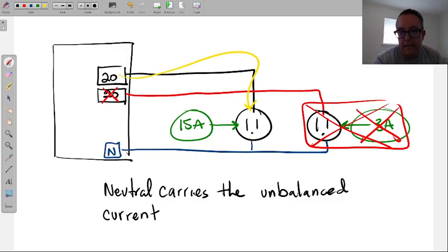And guess where those 15 amps go? This is alternating current, meaning it goes everywhere. And now this neutral on that other outlet that was supposed to be off potentially can have current. When can it have current? If, again, somebody disconnects this neutral.